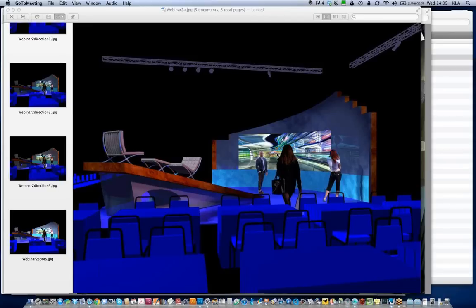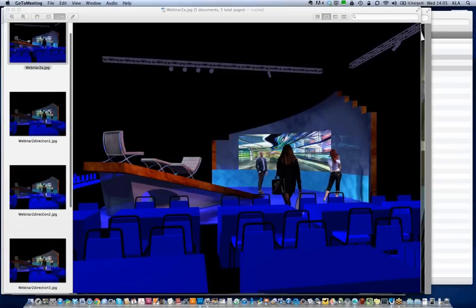The wall makes use of a number of features that are really only available, I think, in the architect module. So I'm going to discuss those a little bit further, but the step wall to the right, I think, is an architect feature. I'm using a wall recess to insert this backlit image, and there's an end detail over here, and the whole piece makes use of the wall styles, which can be quite powerful as a design tool.